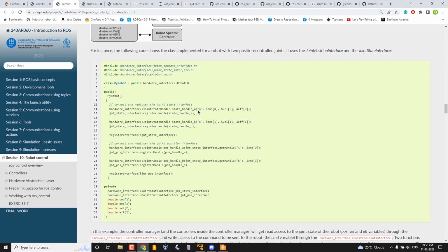So the real hardware is ready, and imagine you can control a motor by publishing a topic. You have written a ROS serial Arduino code, and that Arduino board is controlling the motor. If you publish something to some topic, the Arduino will be writing values to the motor, imagine. And if you subscribe to one topic from Arduino, it will be giving the encoder value.